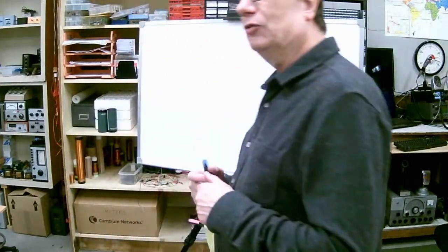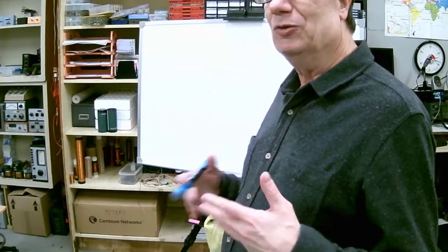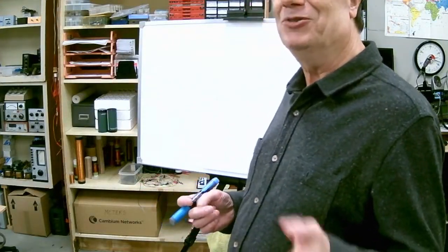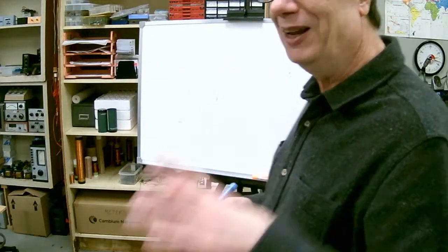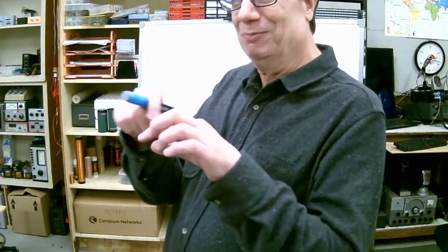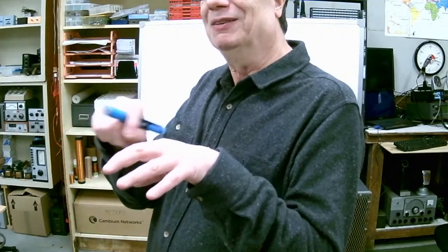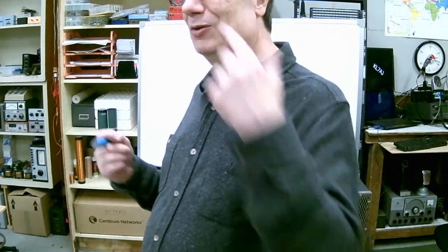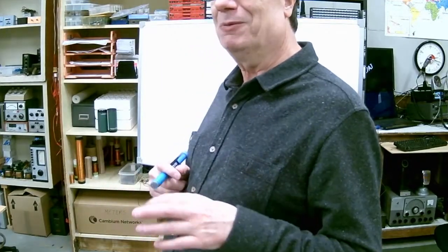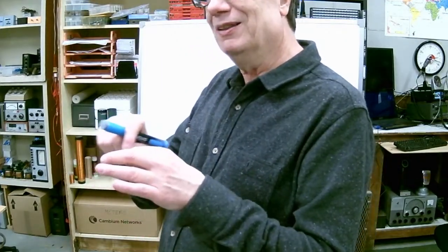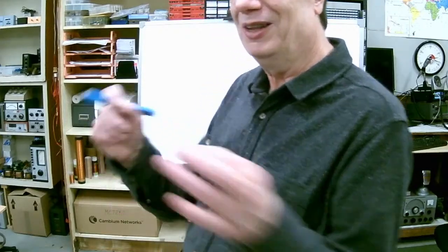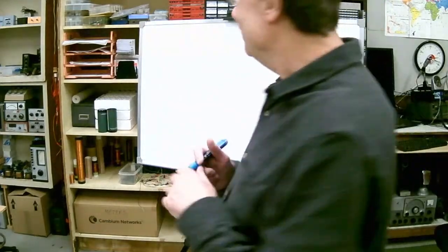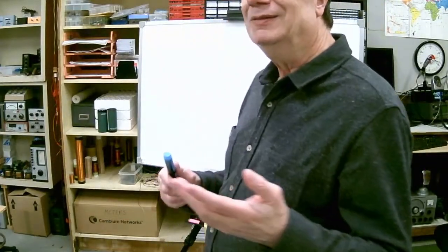So, crystal radio was simply a tuned circuit, and he used to always play around with these razor blade radios. Gillette used to make these blue blade razors, and you take a pencil lead and the Gillette bluing on it would also form a semiconductor. So you take a set of headphones, a piece of wire out there to pick up the station, and then you move the diode around to get the sweet spot, so then you could demodulate the audio and extract it.